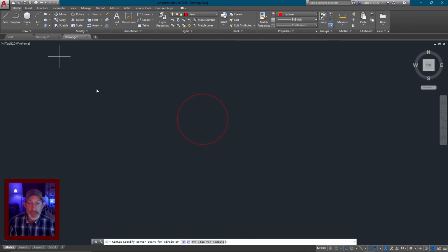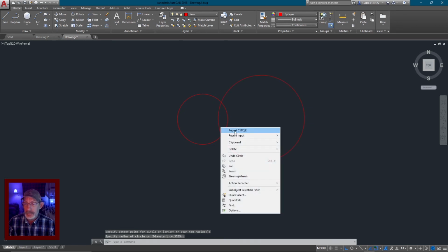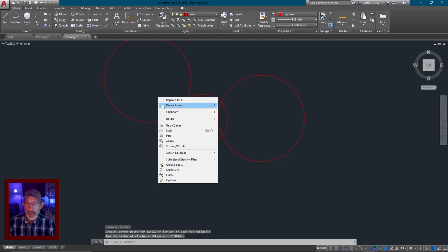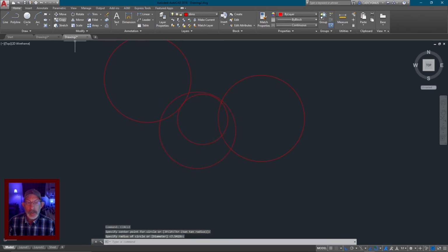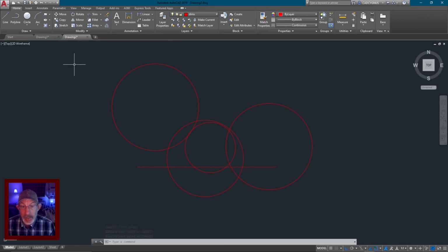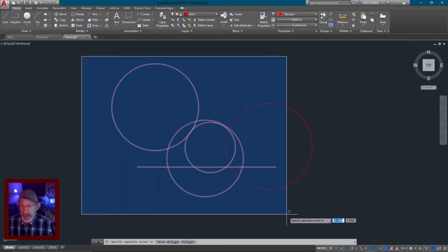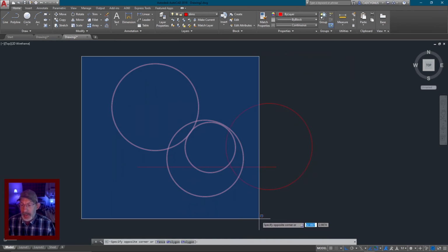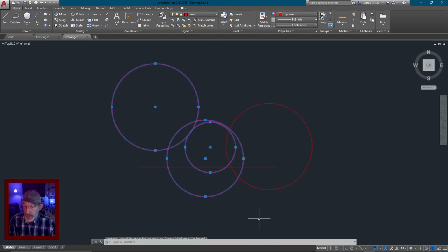Now watch, I'll show you what I mean. I'll do this again, and again, and I'll add some lines to it. Okay, so in this selection box, if I hold it down and select it with a blue box, it's only going to select, and if I pull it back, I'm showing you this now, it's only going to select the things that it contains completely, okay?